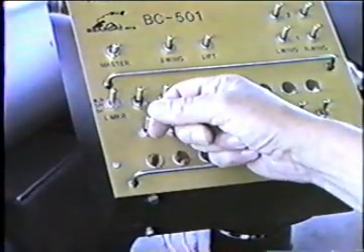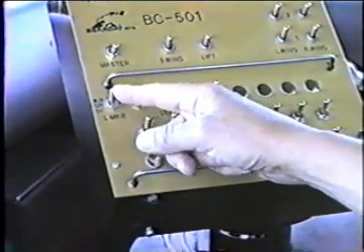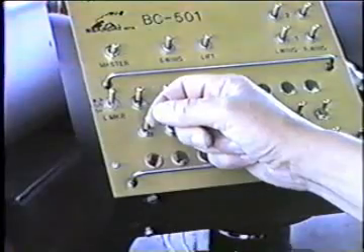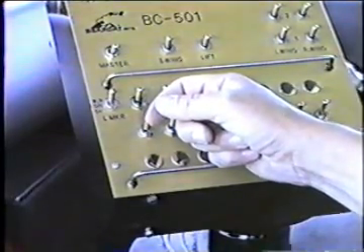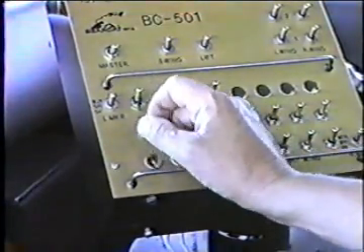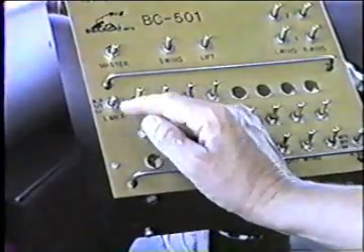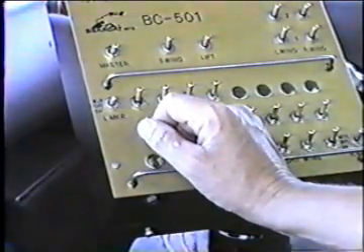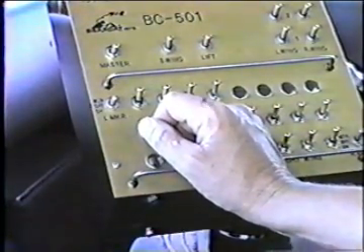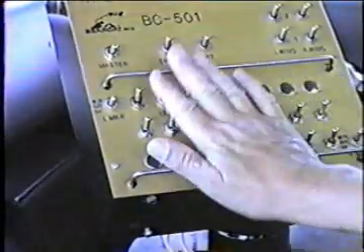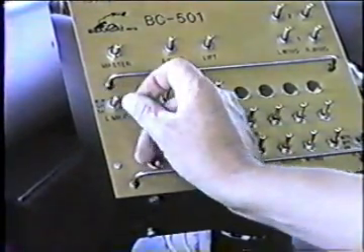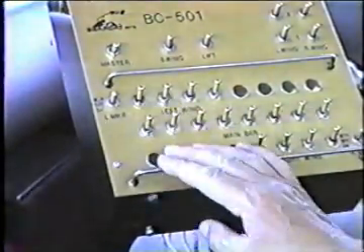This truck is a 16-foot spray bar with both markers turned on. Then we'd have 16 foot 8 inches of full coverage. Center position is off. In the down position, the line marker comes on by itself. That's when we want to mark out a line. We don't have to fool with any of the other switches. Just turn that on, mark the line, and turn it off when we're done.